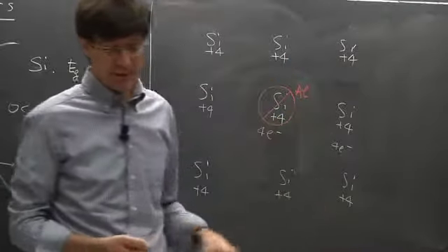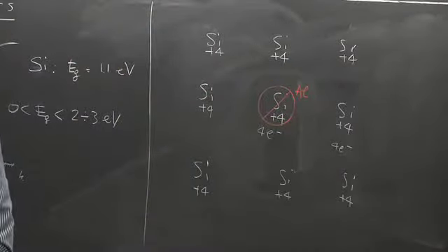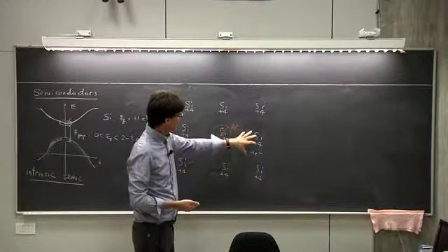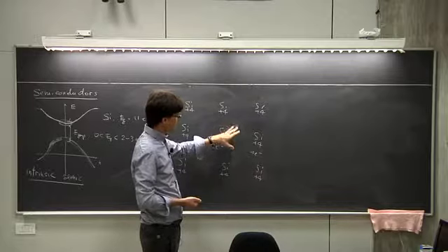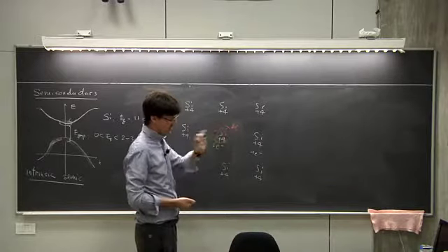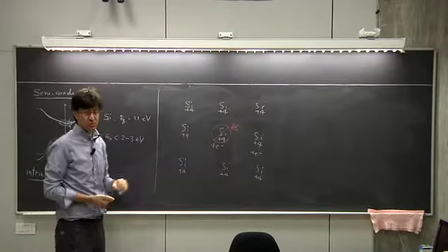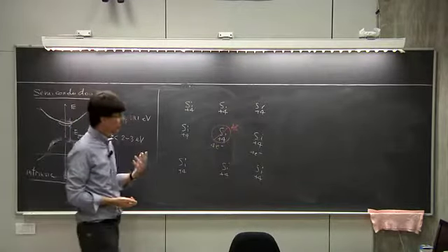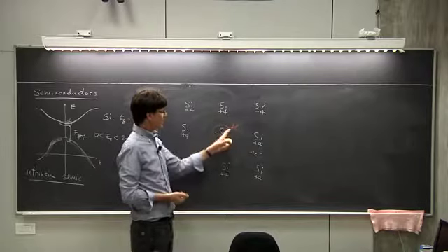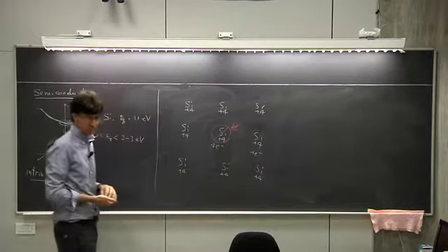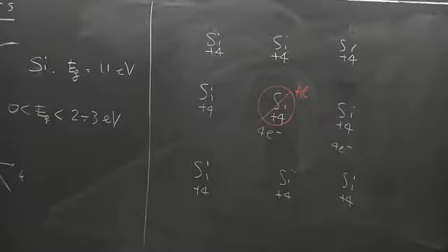So aluminum is close to silicon in the periodic table, and so it shares some of the chemical properties of silicon, at least locally. So the most stable location of aluminum, if you throw a little bit of aluminum in silicon, is to sit at substitutional sites. Substitutional means that it sits on sites where there is no silicon, and silicon is replaced by aluminum as an atom.